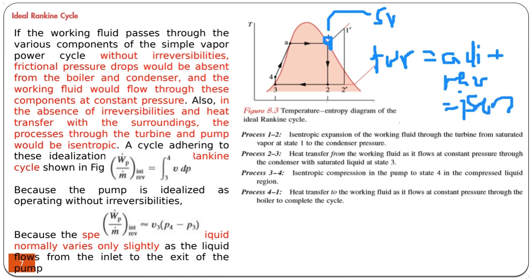You can see the isentropic relation here, because this is entropy, so you can see that the entropy does not change when it expands inside the turbine. At the exit of the turbine, it gets into the condenser, where its phase is converted from gas or mixture of gas to liquid. So here we have saturated liquid.